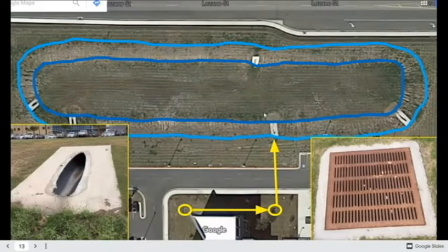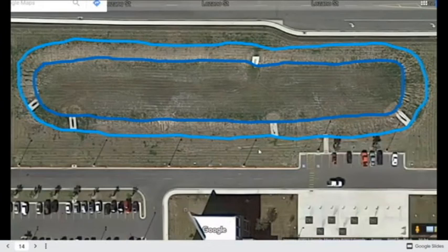If you notice, you can even see it's a different color in front of it. They pour some larger gravel there, and that's to work with erosion so that you don't have it eroding the bottom of the dirt here and eventually getting water under the structure, which maybe over a decade would cause it to drop and crack the piping, and then water would get under the street and cause some pretty serious, what's it called? Pits. When the ground underneath it starts getting washed away.